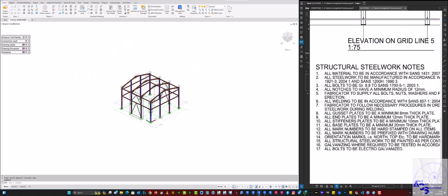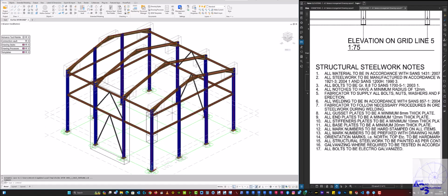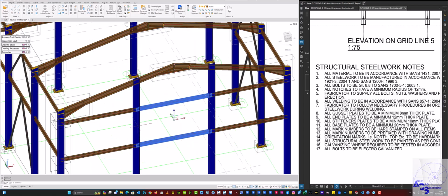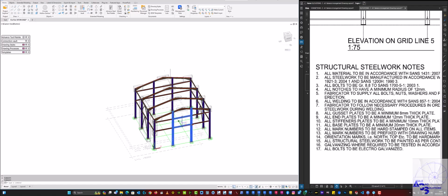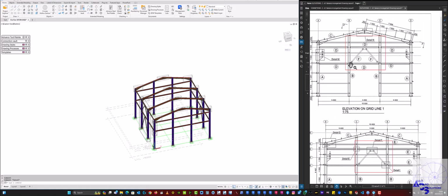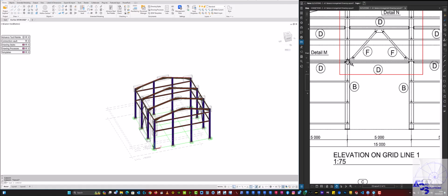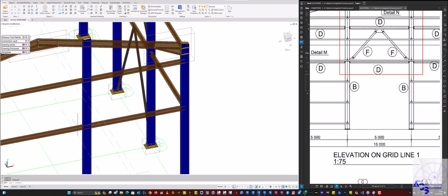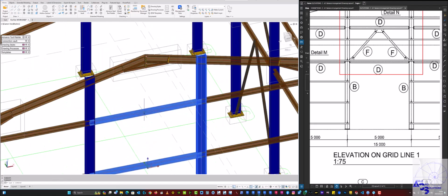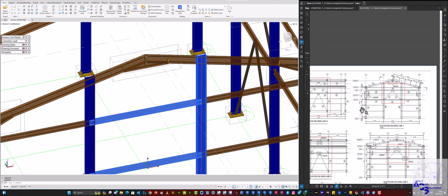So guys, please continue, do some practice, and add the other bracings connecting to these. Then mirror them to the other side as per the design, as you can see. These bracings are going straight to the middle of the column, the intersection of the column and the tie beam. That intersection is where our bracing is going, to the middle of this tie beam centrally. So let's practice, add those, and then I will see you in the next episode where we will add roof bracings.